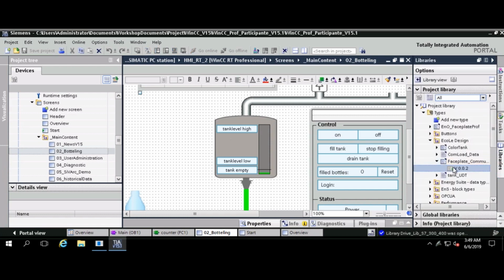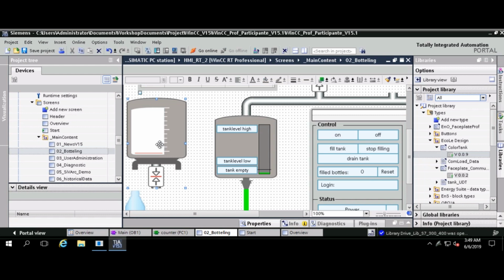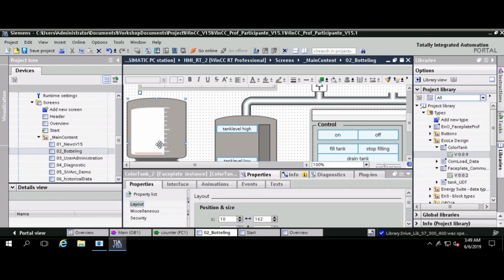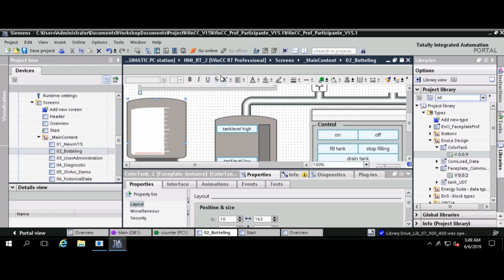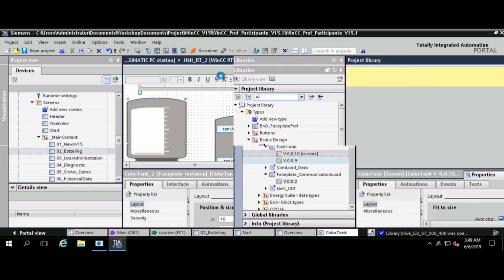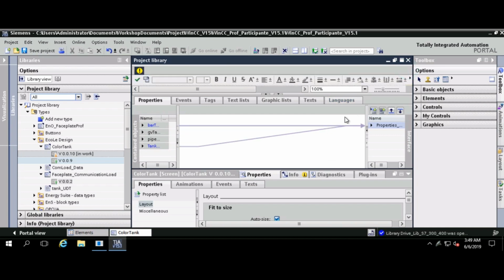And now, we're using a faceplate, just to remind you. Faceplate means we always put the properties to the outside of the faceplate, which we can then link in the project. So that's actually the same thing we do here as well. You already have some properties put to the interface of the faceplate, which are listed on the right side of this editor, and we can also see which object is connected to which property here.